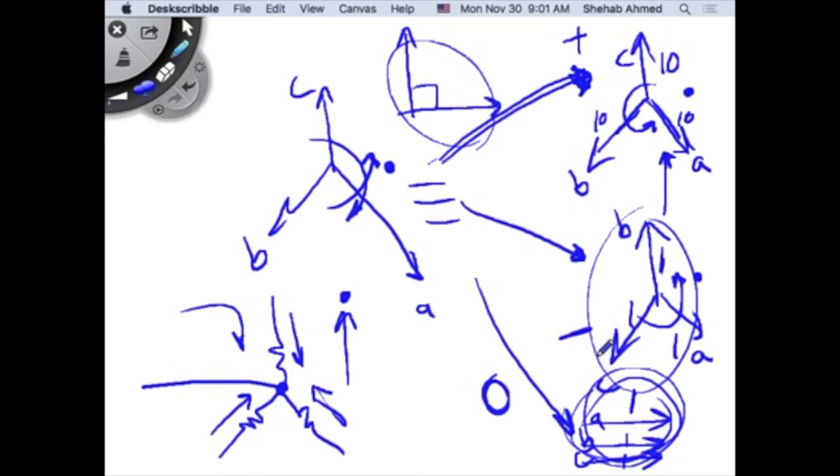This current will create torque, but that torque is not going to rotate. It's stationary torque. So this can plug the motor, can brake the motor. This can rotate in the opposite direction, and this will rotate in the direction you want. So if you have too much of the negative sequence or too much of the zero sequence, it's a problem.